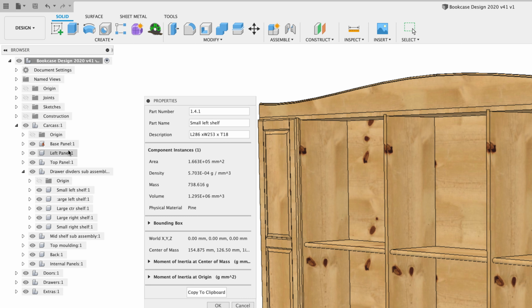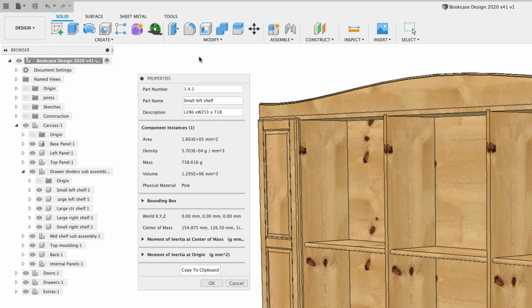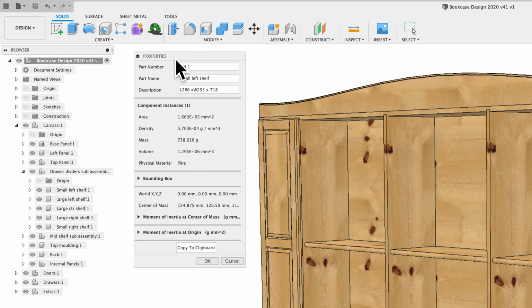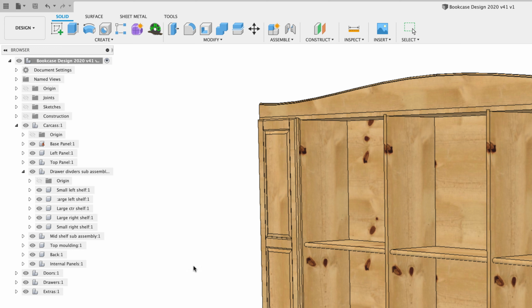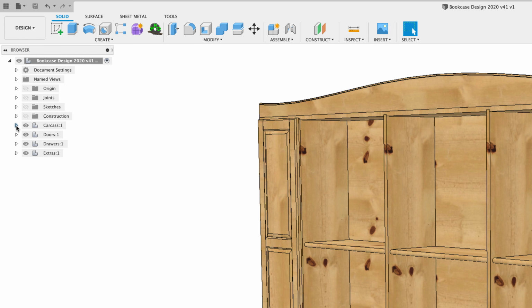So by grouping these together in these workflows, number 1, number 2, number 3, number 4, the subassemblies is a major increment, 1.1, 1.2, 1.3, 1.4, and the sub-subassemblies or the components as a minor increment, 1.4.1, 1.4.2, etc. It just gives me a bit of a part number, and these numbers then I can use in the workshop to identify the components. So it's well worth going ahead and just cleaning up that menu.